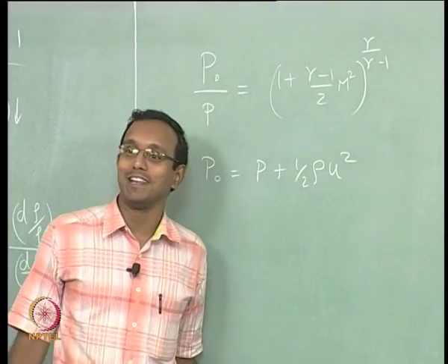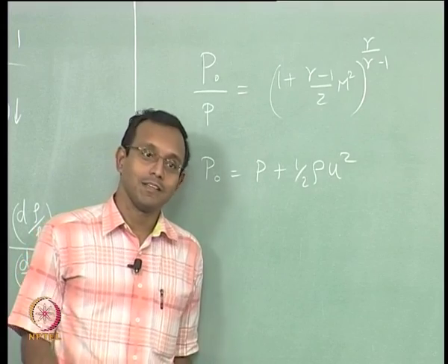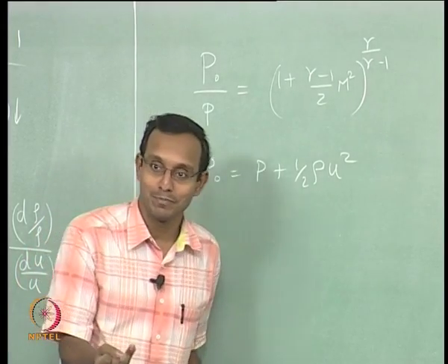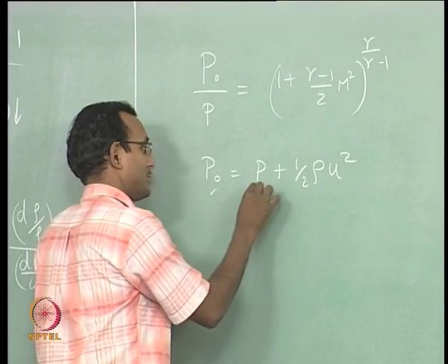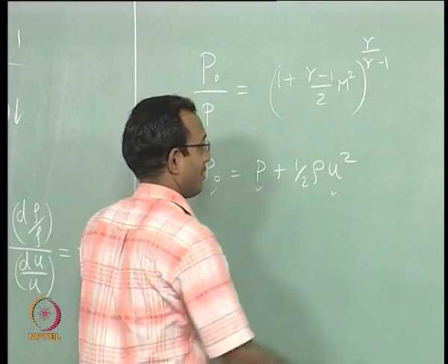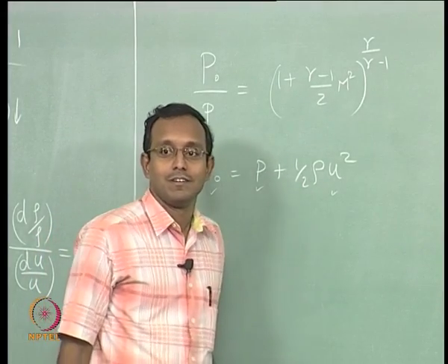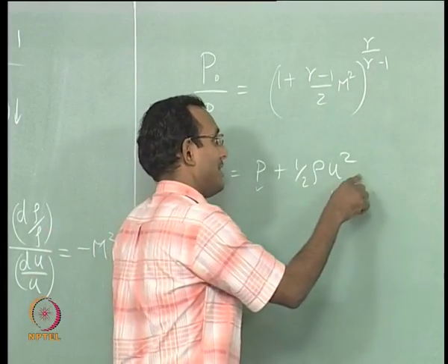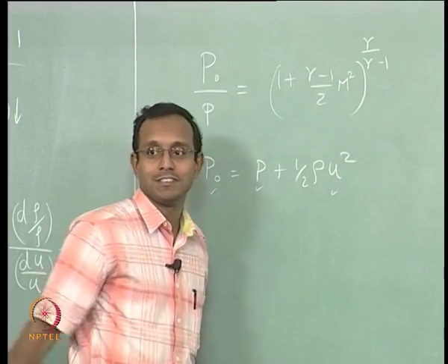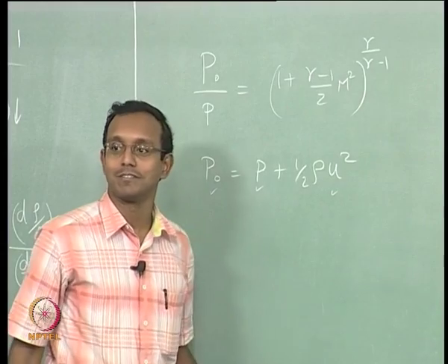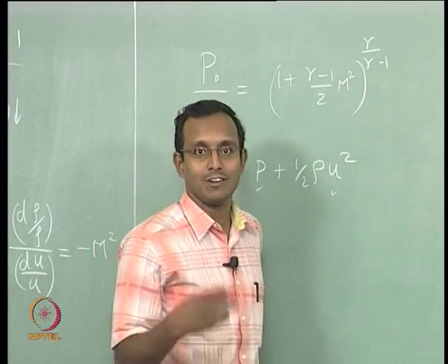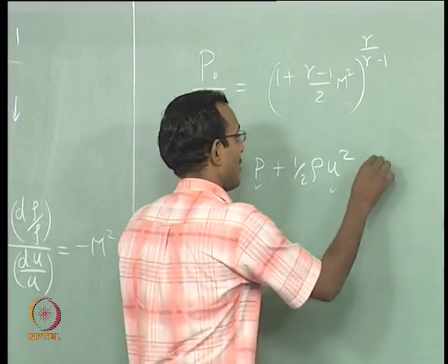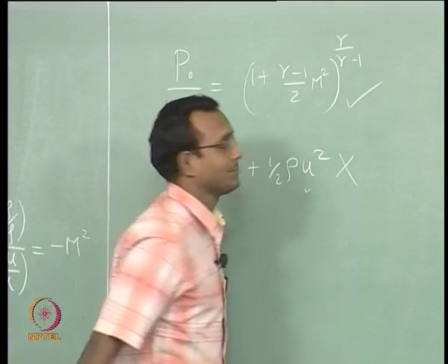Aerodynamics people typically use this with a pitot probe and static probe. Okay, they are going to use these two numbers from there and they are trying to get velocity here. But remember that this is only the first two terms of the expansion of this, there are a lot more terms available here. Okay. So, we are in the compressible flow world, we will not use this formula, we will only use this formula.